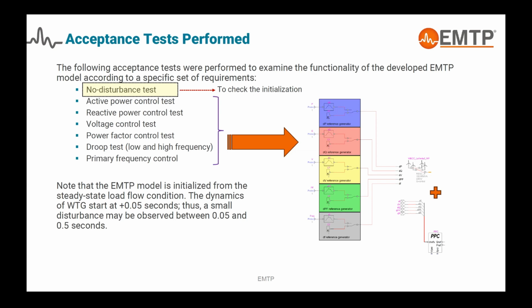the deviation in terms of power reference, Q reference, voltage reference, power factor reference, and frequency reference that we are setting here at the PPC. As you can see, these signals go through these pins, and these pins go directly to the PPC. So once you play with these switches and these tables that will change the reference at the PPC, you can run these tests using this approach, right?